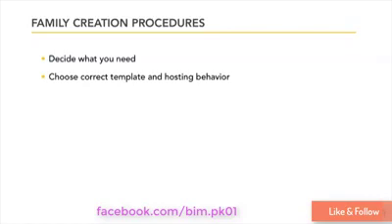If you choose a template that requires a host, then the family you're building will be required to be attached to that kind of a host element when you put it in a project. So it's a pretty important decision, and you're being forced to make that right away at the beginning. So it's something you want to think about carefully before you get started, and we'll see some examples of that shortly.